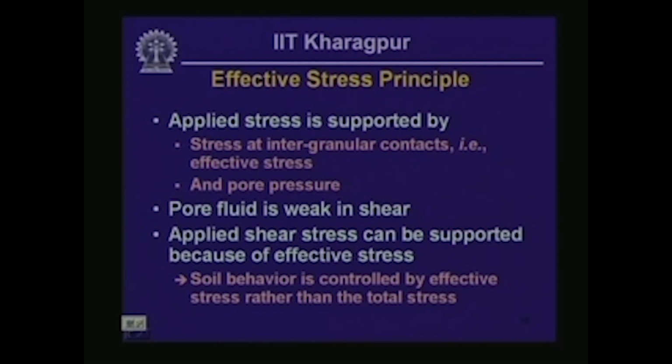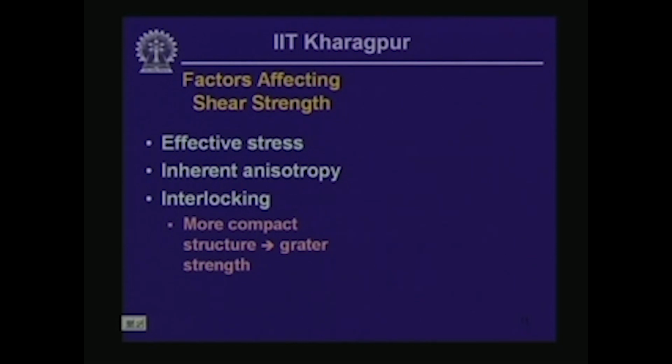So soil behavior, the shear stress and shear strain response, is controlled by effective stress rather than the total stress. This is the effective stress principle introduced by Karl Terzaghi in the early 1900s, which led to the development of the science of soil mechanics and geotechnical engineering. It is a very important principle, actually seminal in fact, that led to the entire development of this field of learning.